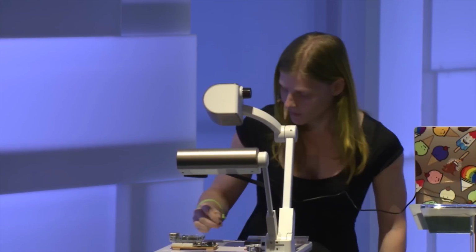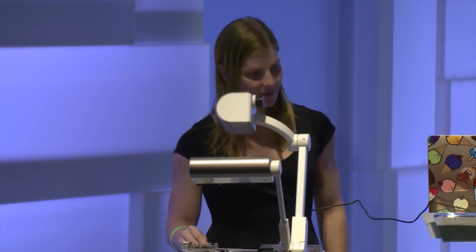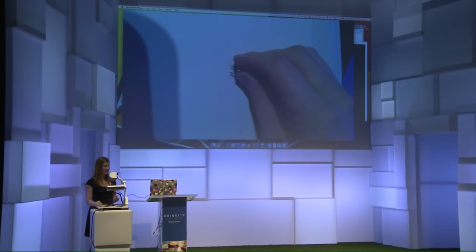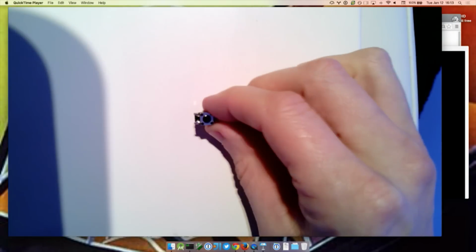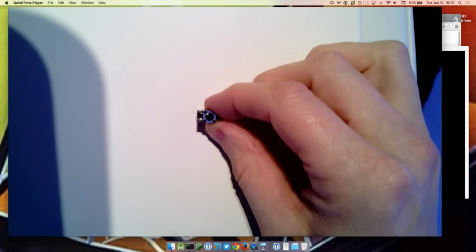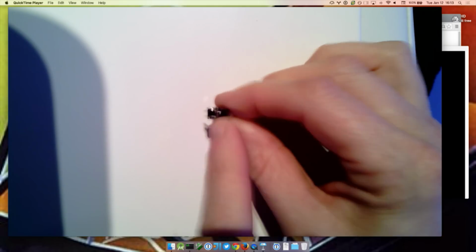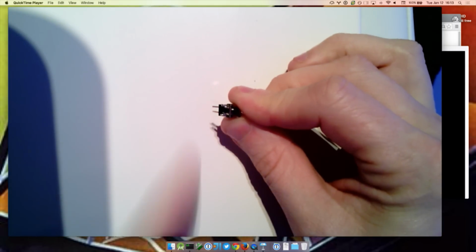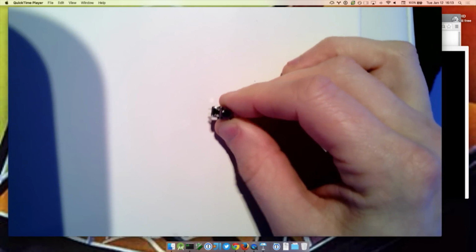10 kilo ohm. Okay, some more components. This is a tiny button. It is a push button. It has 2 pins that stick out of the side. When you leave it alone, no data is moving across it, so it is just open. When you push it down to close it, when you push the button and feel the click, the 2 little wires are connected, and it allows electrons to move from one side to the other. So we will be using that as this very simple digital input.